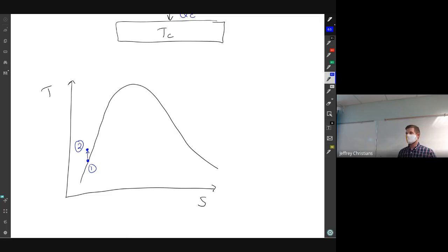So what's going to happen is we're going to heat up a little bit, and then we're going to start to boil. So we heat up here, and then we get to there, and then we start to boil. But we're not done yet. We're actually going to let it heat up beyond the boiling point a little bit, right? Because we couldn't take this. We have problems designing our turbine. We couldn't have this vapor liquid mixture in our turbine. So we want to make sure we have only vapor in our turbine, or almost only vapor. We can have a little bit.